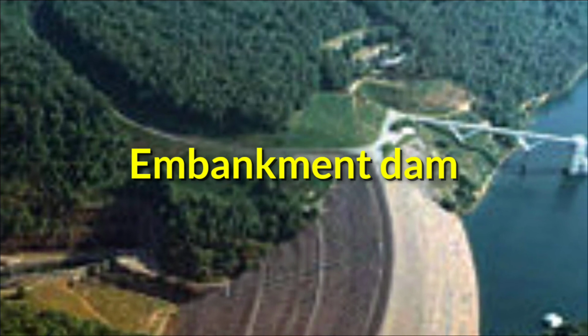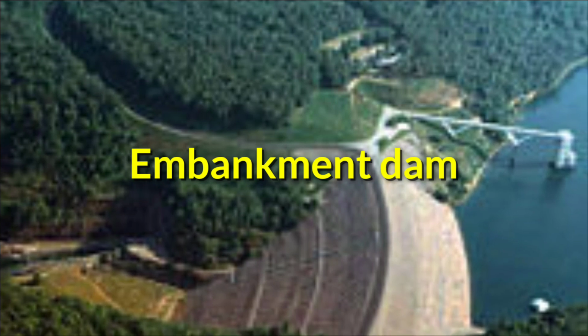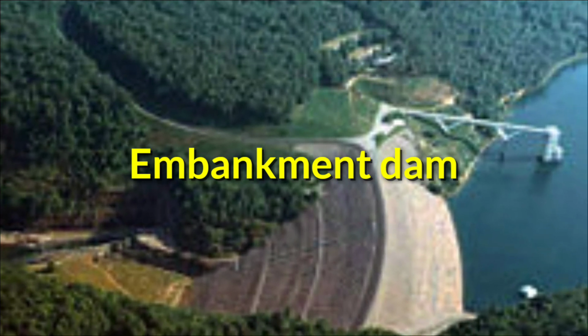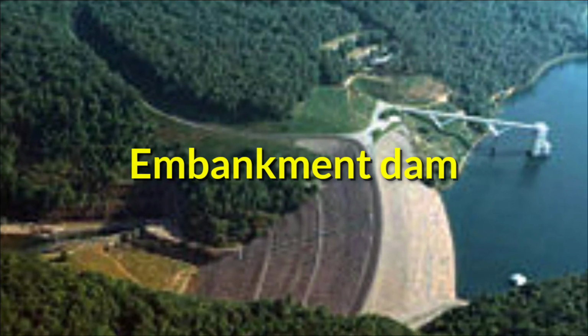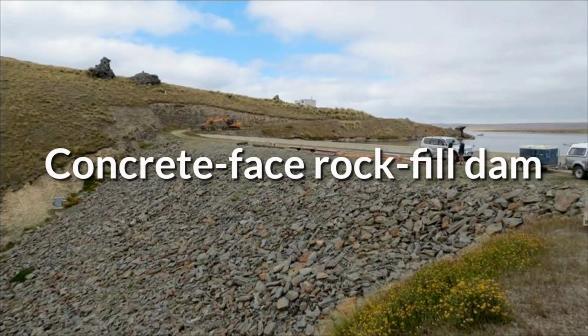Thus the term embankment encompasses both the earth and the rock fill dams. These dams are also referred to as dikes, or simply embankments or banks. Next one is the rock fill dams, or the embankments of rock fill, which is compacted free-draining angular earth with an impervious zone. The earth used often contains a higher percentage of large particles, hence the term rock fill is given to this dam.